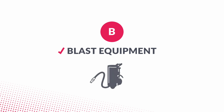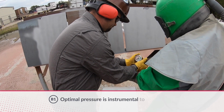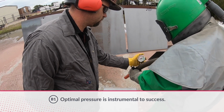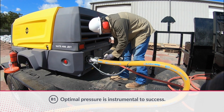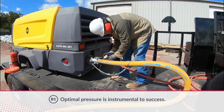Part D, blasting equipment. Having optimal pressure is instrumental to success. The number of blasters, type and size of nozzle and blast equipment affect the overall efficiency level of the blast operation. When attaching additional equipment, the compressor should be sized appropriately to maintain sufficient air pressure at every nozzle.